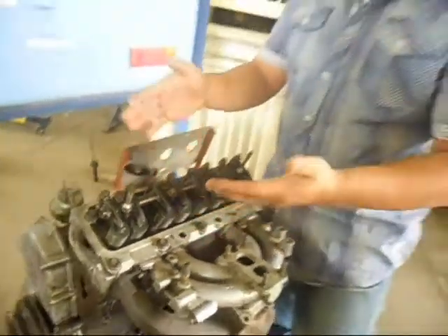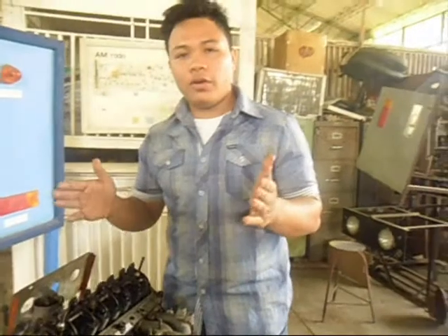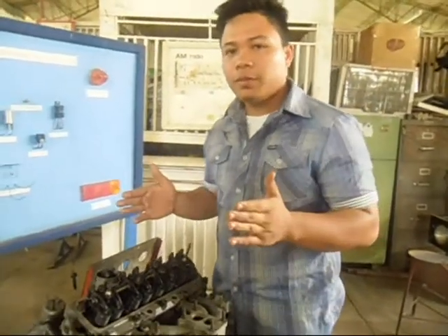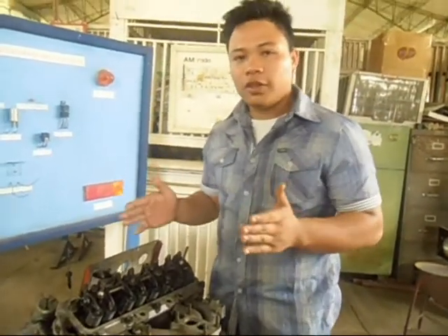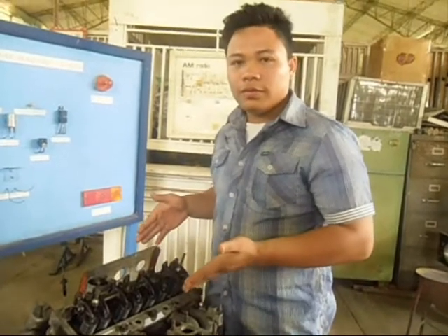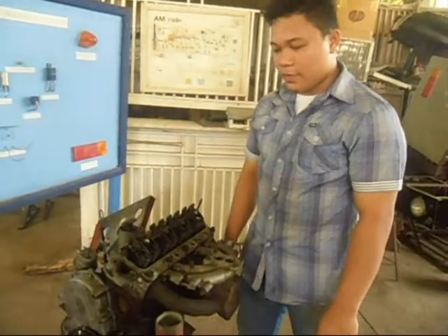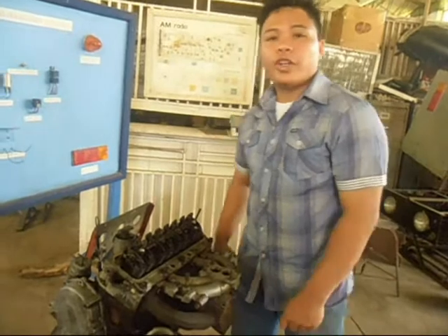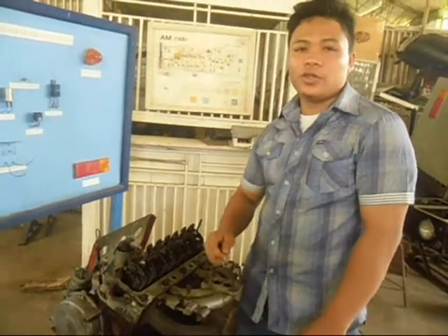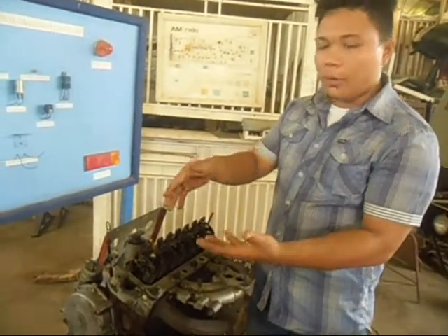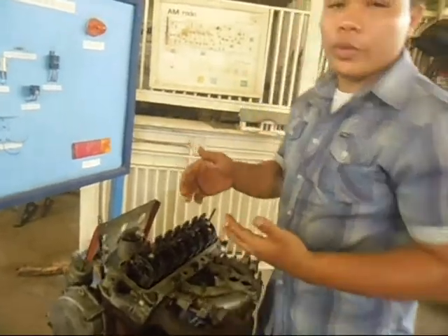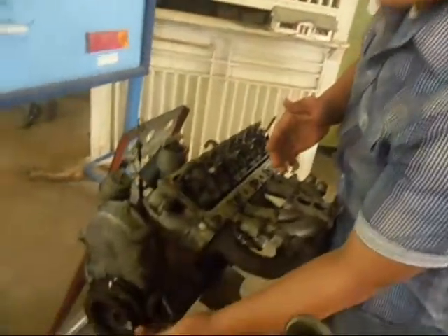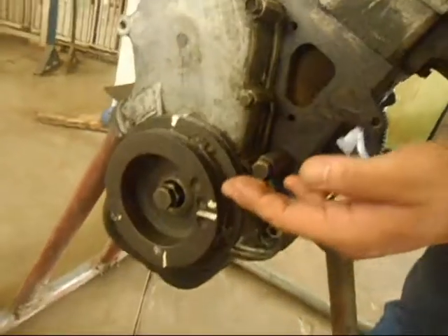We will adjust the valves. To identify the piston sequence or piston numbering, we could use this pulley as our clue.